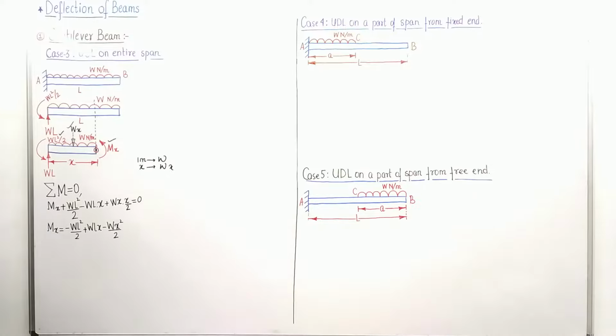Here we go. So, what do we do? Instead of writing this Mx, let me straight away write this: EI y double dash. Y double dash stands for d2y by dx square, the second order derivative. Y dash stands for dy by dx, and simply y is basically the deflection. Okay, here we go. So on integrating this, you have this result: